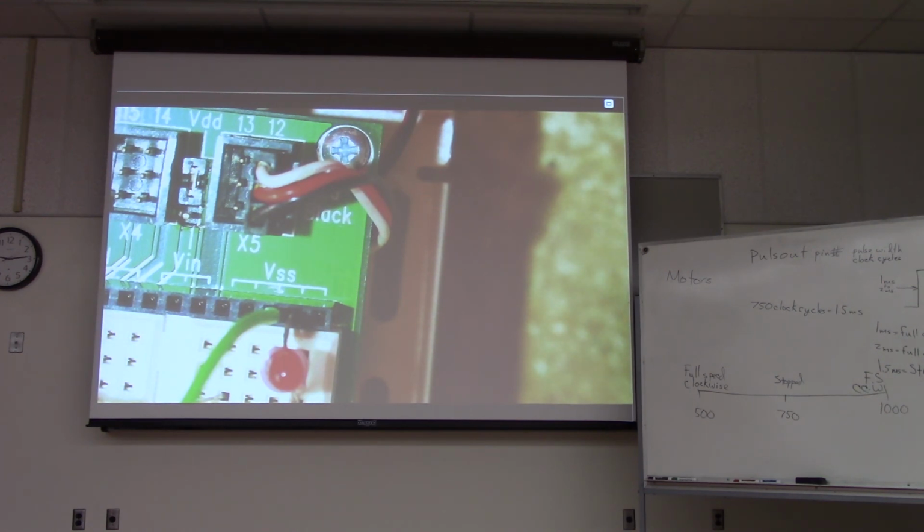Sometimes we have a circuit with two batteries in it, and ground might be the point right in between those two batteries. So really, sometimes ground has no physical meaning at all. Sometimes it's just a point that we pick on the circuit. Sometimes it does have a physical meaning where that part of the circuit could be attached to a chassis.